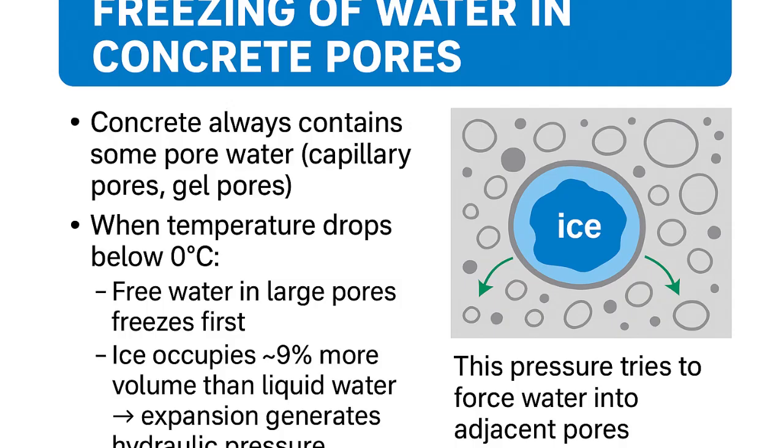Expansion generates hydraulic pressure in the surrounding unfrozen water. This pressure tries to force water into adjacent pores. Now, what will happen without air entraining agents?